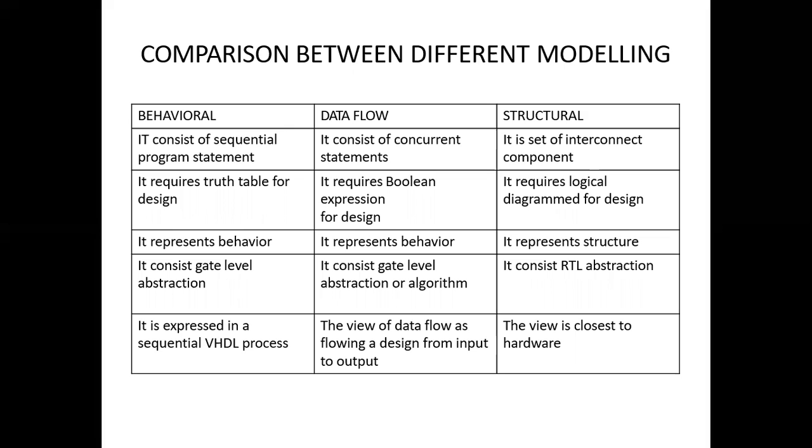And structural modeling. It is a set of interconnected components. It requires logic diagrams for design. It represents structure. It consists of RTL abstraction. The view is closest to hardware. So this is the structural concept. These are the points we need to know about these models, that is behavioral, data flow, and structural models for execution.